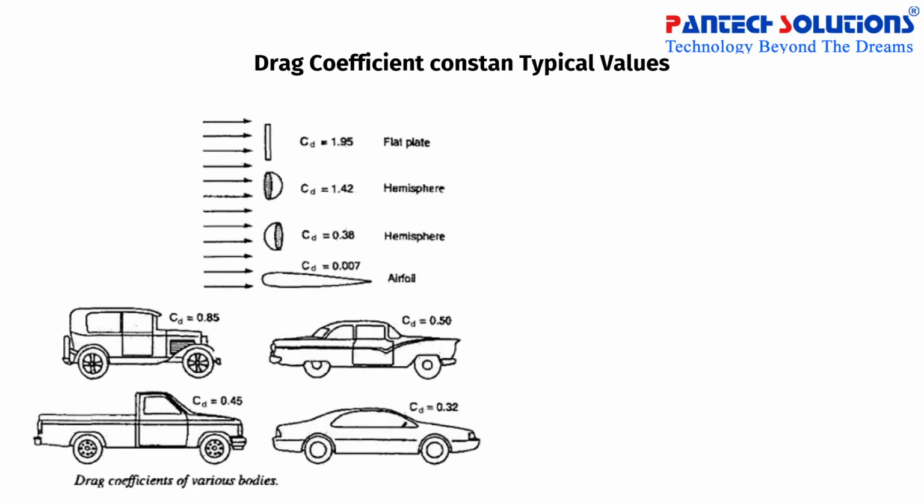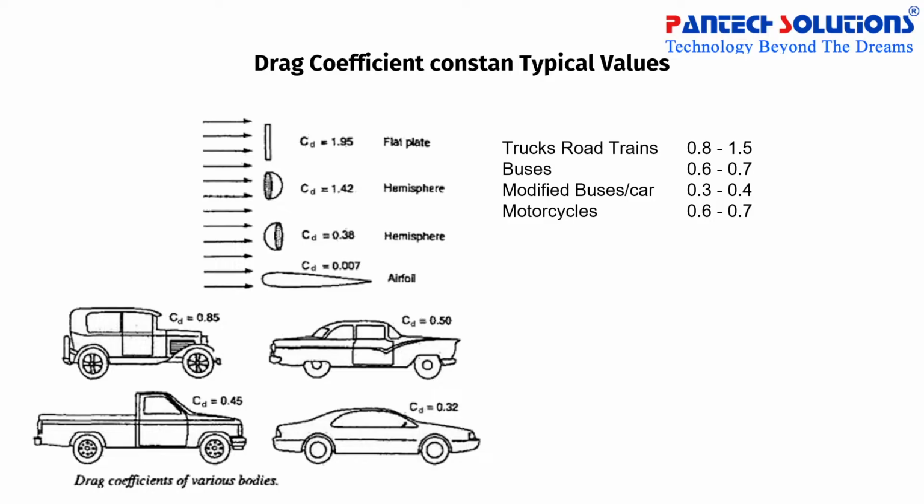In the aerodynamical drag force, we capture different values based on the vehicle structure. I will show some structures here. The first one is an old type model, where the drag coefficient value will be 0.85. The reason is that there are two flat surfaces inside, one flat surface and this L type.